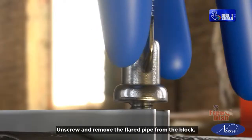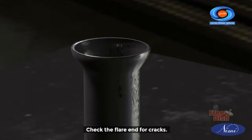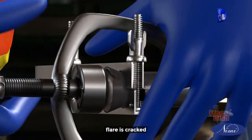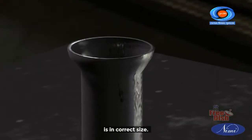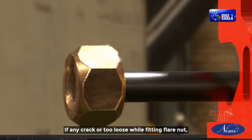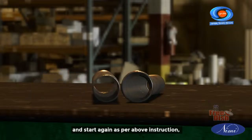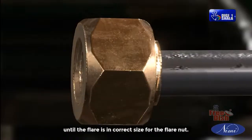Unscrew and remove the flared pipe from the block. Check the flare end for cracks. Note: because the cone was screwed down too quickly, the flare is cracked. Make sure that the flare is the correct size. If there is any crack or it is too loose while fitting the flare nut, cut off the flare and start again as per the above instructions until the flare is the correct size for the flare nut.